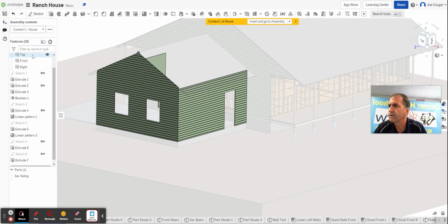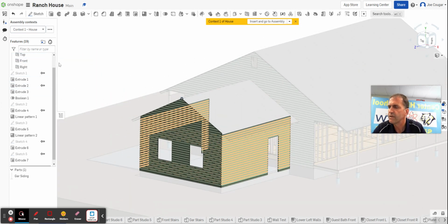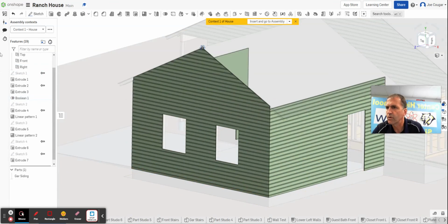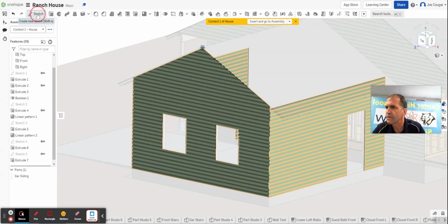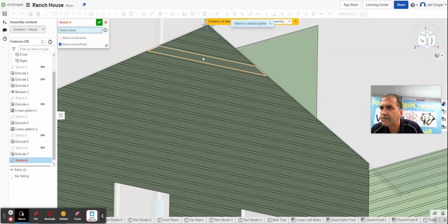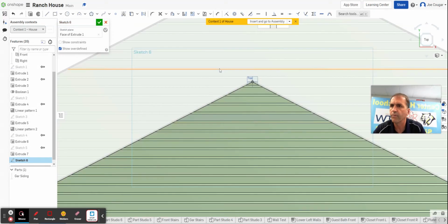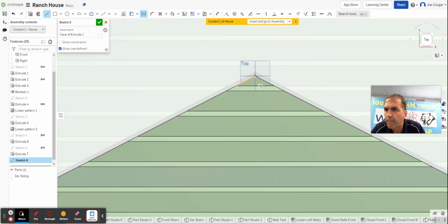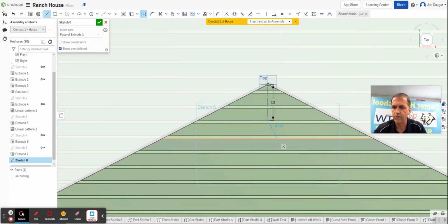So we're going to make an 18 by 24 vent, just like we did on the house. Because that's what's going to look best if they're all kind of the same. So we sketch on a flat surface on the end, and for normal, let's make a line that is a construction line, just like we did last time. That is from that little peak right there, going down 12 inches. Okay, so we get ourselves a spot to hook to.